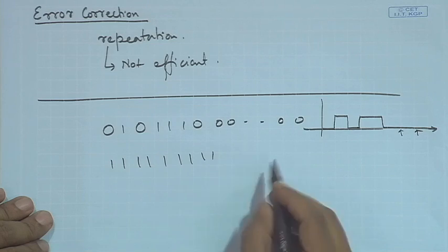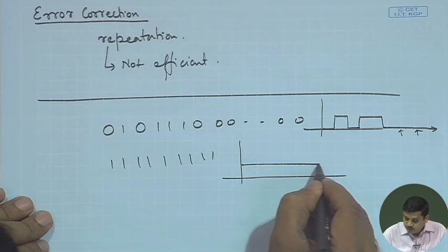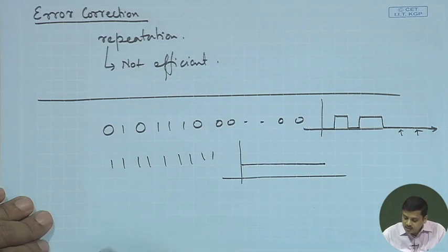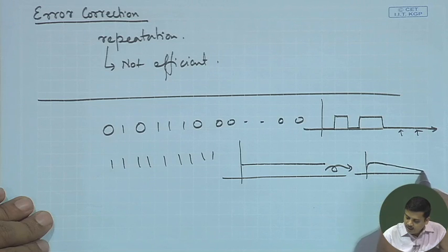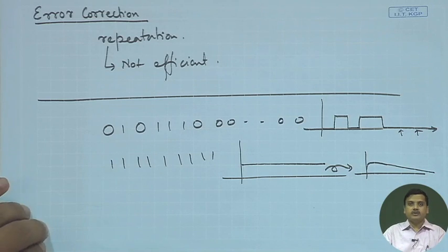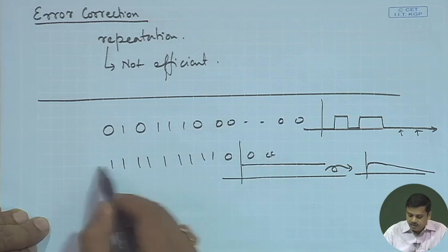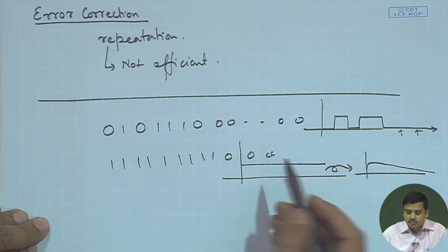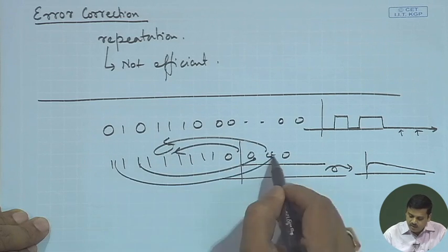If you look at this particular sequence, you would be generating this. At the receiver, this might cause a problem, because there would be RC circuits, which slowly decay, and you are not able to distinguish between a 0 and a 1. It will slowly convert to 0. So, in order to avoid such situations and to bring back synchronization, usually you are not going to get a whole sequence of ones throughout, that is almost meaningless. You are going to mix the zeros and ones in a random fashion.